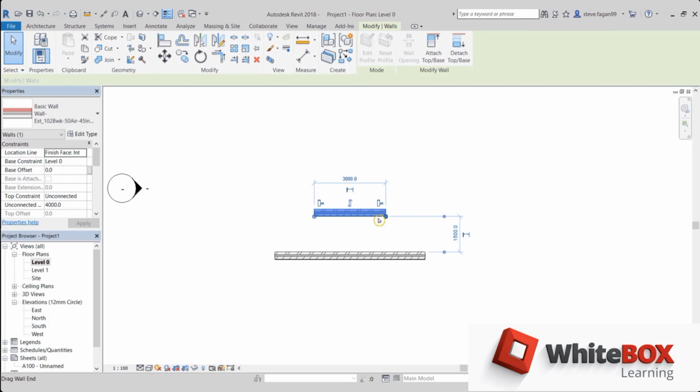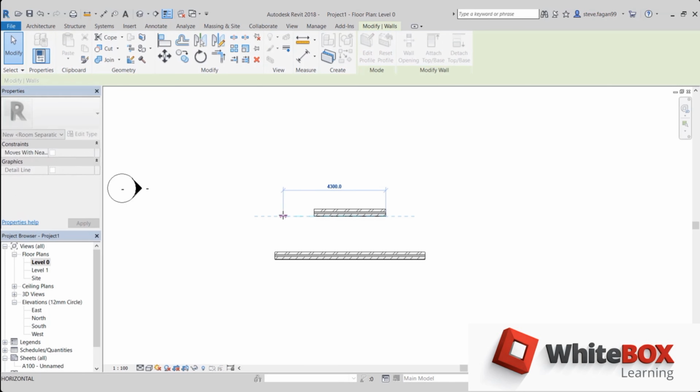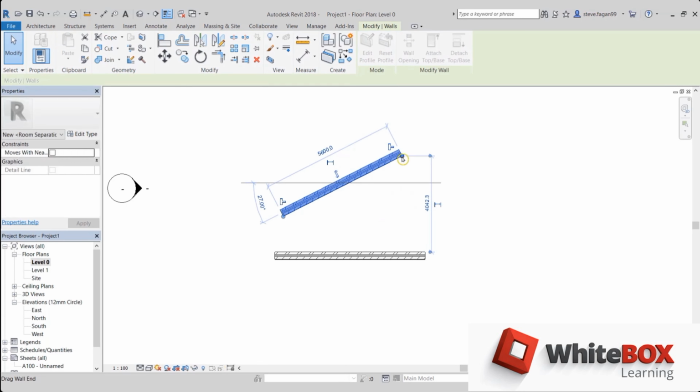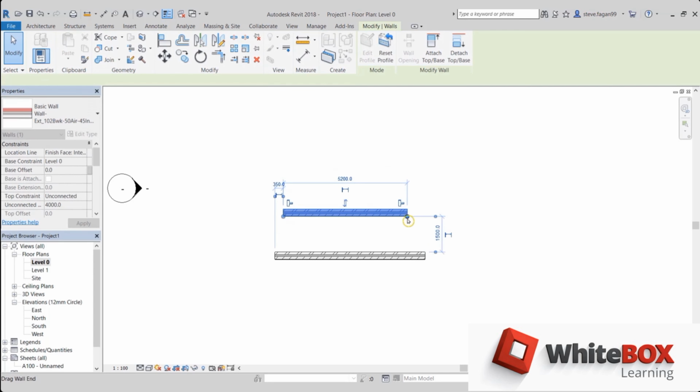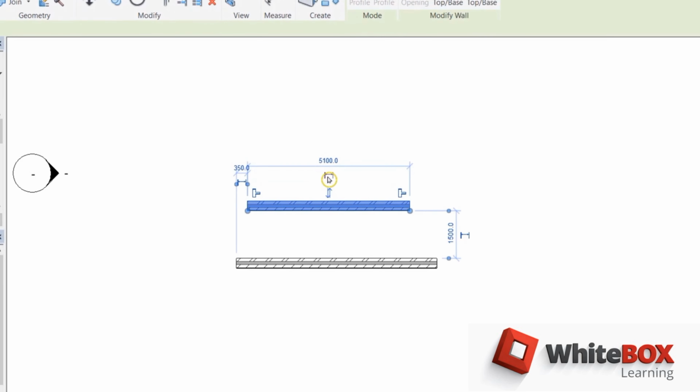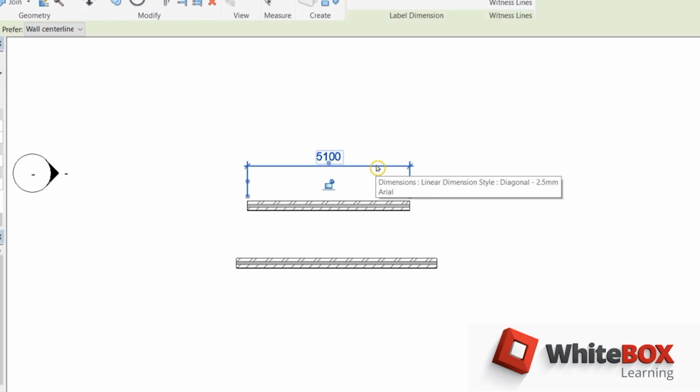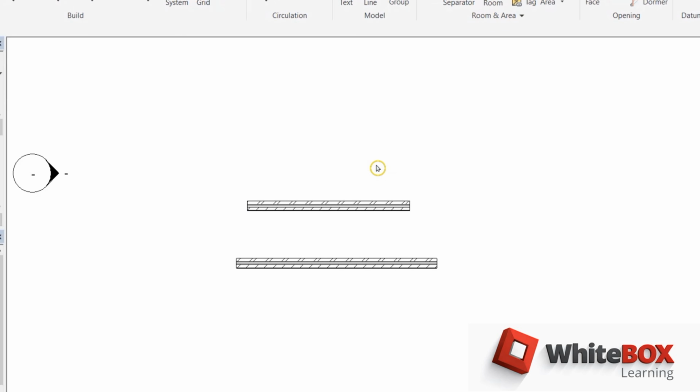As well, we have the grips, which I can click and drag to extend out the length. I can also add an angle with those grips. As well as the temporary dimension, below it, there's another dimension symbol. If selected, we'll make that temporary dimension into a permanent dimension. To then remove it, we'll select it and delete it. I deleted it using the delete key on the keyboard.